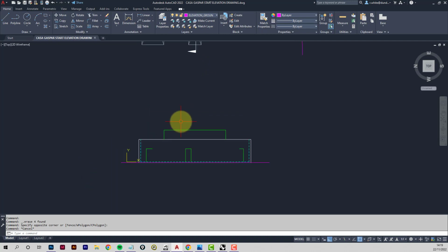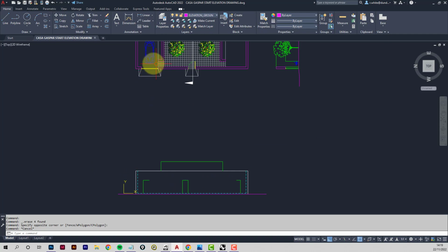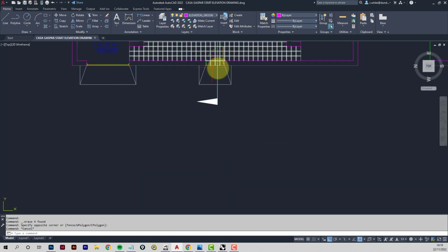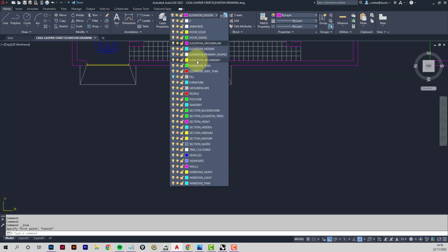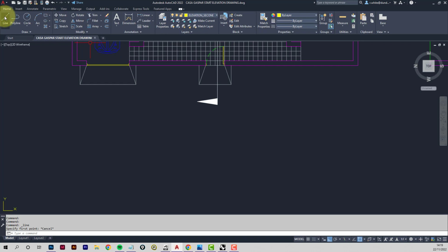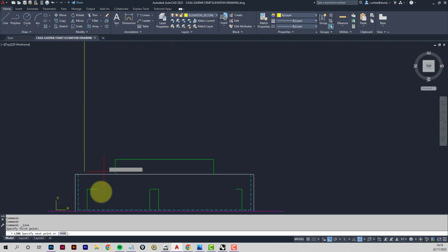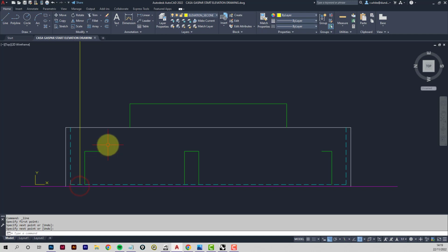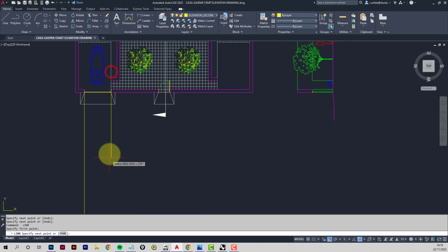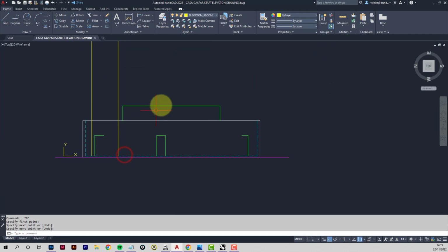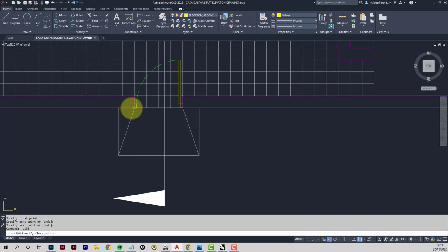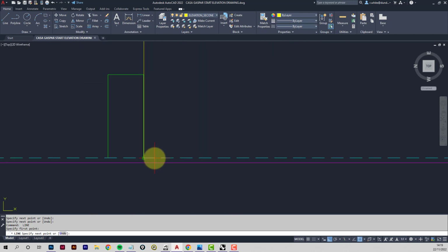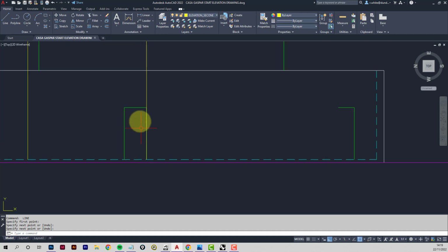Okay, right, we've got now to consider these two openings. We've got the garage door and the main entrance, so let's project lines down from there. Let's change layers, so we're on the elevation secondary layer. Line, just pull those down. I'm going to hit that hidden line. Okay, let's go here, side of the door. That's coinciding with an object that's already there, so let's just delete that.